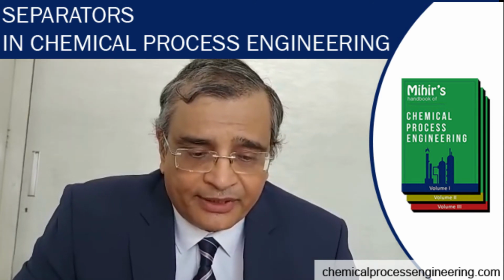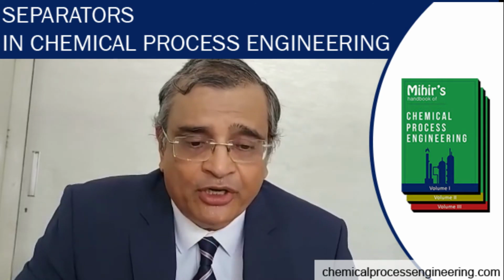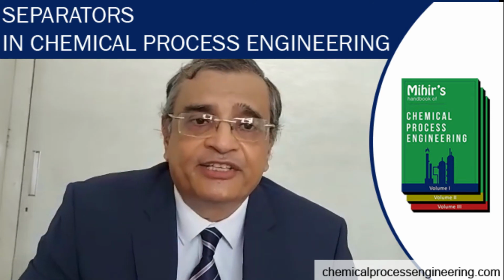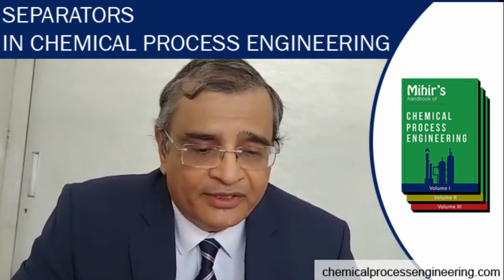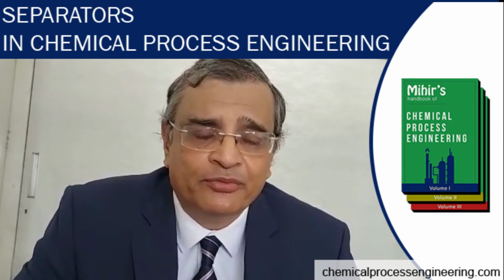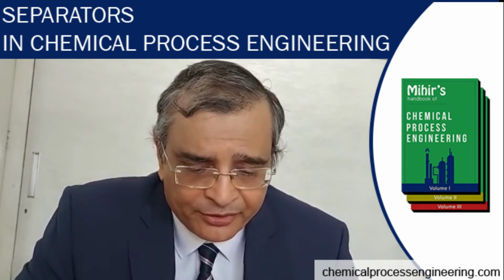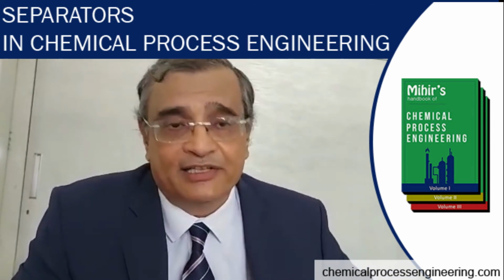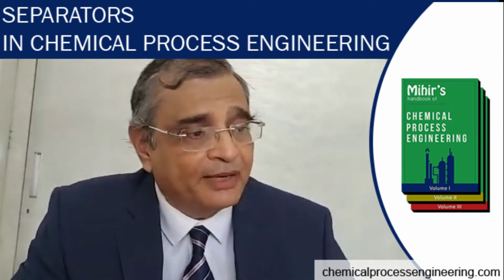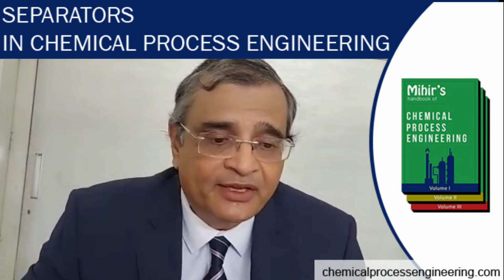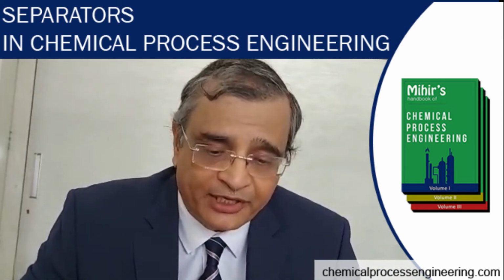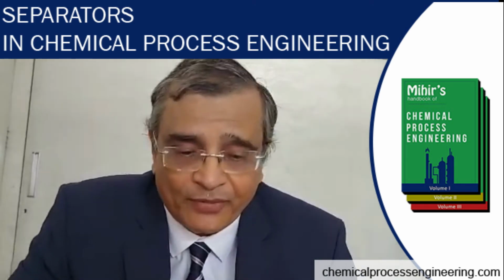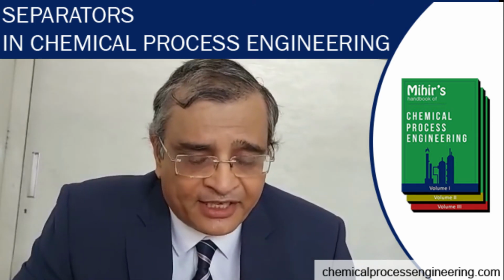Now there is a certain thing called a surge volume. Suppose you have a small plant like the amine regeneration unit example I had given you. There it is not much relevant to have a surge volume, but suppose your feed drum is collecting the feeds from many oil wells. Here you have pipelines running over many kilometers and there is a chance of surge occurring. So it is very important that in such a vessel you also have a surge volume as part of the design. So this is as far as the design is concerned.